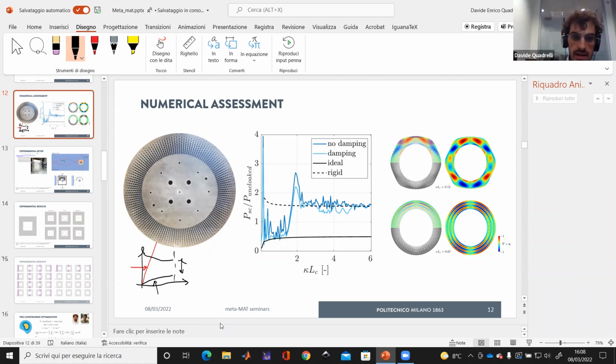So each one of these unit cells has a different dispersion relation, but in the end, we computed that all of them have a common single mode bandgap. So there should be a frequency range in which only longitudinal waves can propagate inside this one. A priori, I was convinced that in this frequency range I would have obtained the best results in terms of cloaking, because that is the frequency range in which the pentamode behavior happens dynamically.